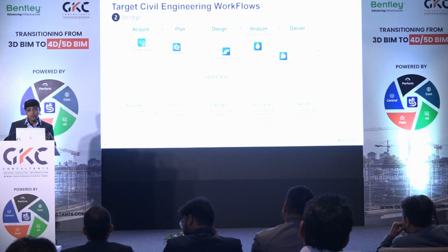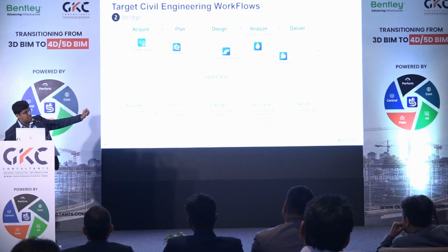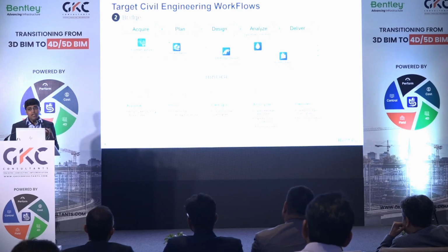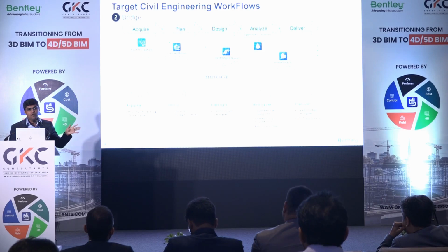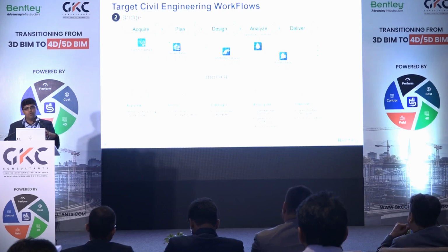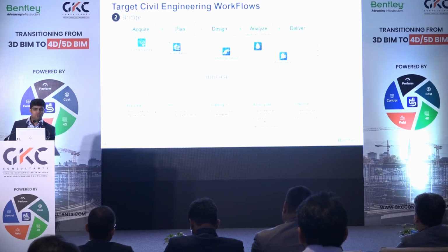And we have an add-on tool known as ProStructure, which is mentioned towards the end, where you can take the entire 3D model from OpenBridge Designer to ProStructure, put in your 3D reinforcement bars, and generate a bar bending schedule, which is usually done in a different product line, or in AutoCAD or CADian. People do all these works in silos. What if you have a complete workflow? Wouldn't that be great? That is what we are going to discuss in the coming 6 months with all the consultants and contractors across the country.